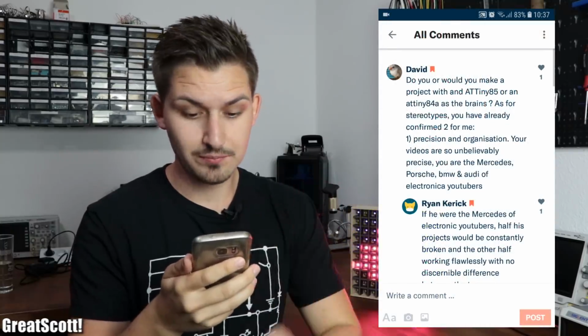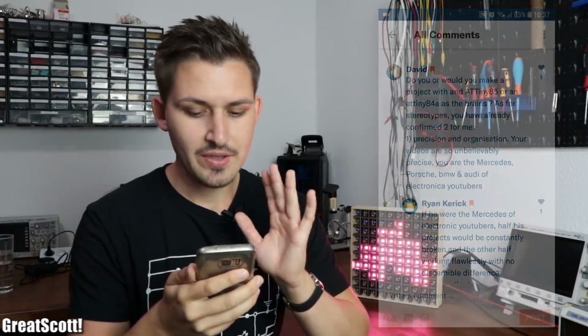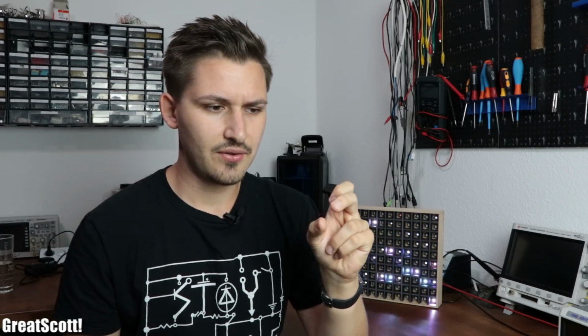The first question from David: do you or would you make a project with an ATtiny85 or an ATtiny84A as the brains? As for stereotype, okay, so the ATtiny85 and ATtiny84, I actually did projects with those microcontrollers because I think they are very handy, very practical. They only cost, I think, €1 or $1. And they have 8 pins, so I think you got 5 input outputs, 3 PWM pins. So yes, I actually used them before.